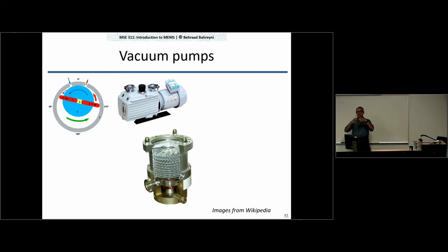So this pump is connected to a chamber, gas molecules at those pressures are moving around, and from time to time some of these gas molecules hit the blades of this turbo pump. Then, through momentum transfer, the blade pushes that gas molecule down towards the blade set below it, and so on and so forth, and eventually to the bottom of this blade arrangement.